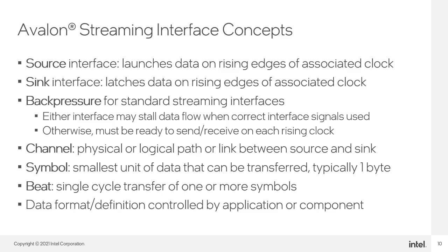Here are some basic concepts about Avalon Streaming that are important to understand before examining the standard itself. Avalon Streaming consists of two interfaces, the Avalon Streaming Source and the Avalon Streaming Sink. A source interface launches data on rising clock edges, while a sink interface latches data on rising clock edges.